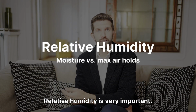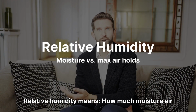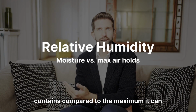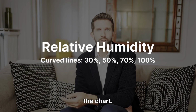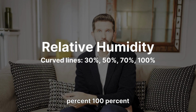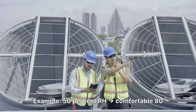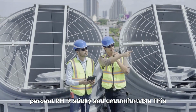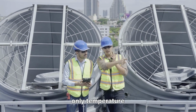Relative humidity is very important. Relative humidity means how much moisture air contains compared to the maximum it can hold. It is shown by curved lines on the chart. Common values: 30%, 50%, 70%, 100%. Example, 50% RH is comfortable, 80% RH is sticky and uncomfortable. This is why air conditioners control humidity, not only temperature.